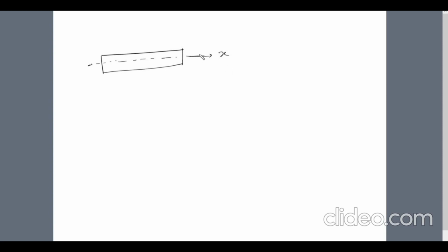Now if it is subjected to only one force P only along the x-axis, then the normal stress that is caused along the x-axis is sigma x. There are no stresses created along the y-axis or z-axis, just one stress sigma x produced along the x-axis. So this is called uniaxial stress. In case of uniaxial stress, the stresses along all other dimensions are 0. There is only one dimension of force, one dimension of stress, that's either along x or y or z.